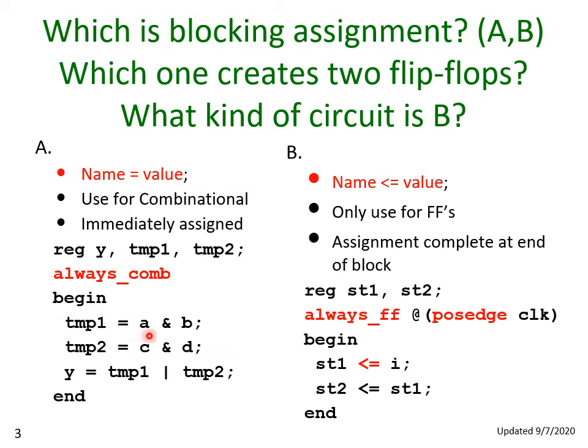So that value isn't available immediately, and at a given instant in time, the value of y would reflect the previous value of temp1 rather than the new value. But when we're simulating behavioral Verilog code, and we only want to describe the logic function, not model circuit behavior and delays, it is useful to have the value available immediately.